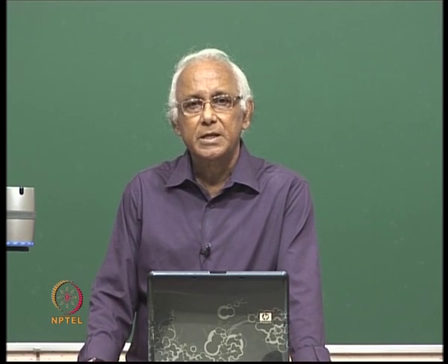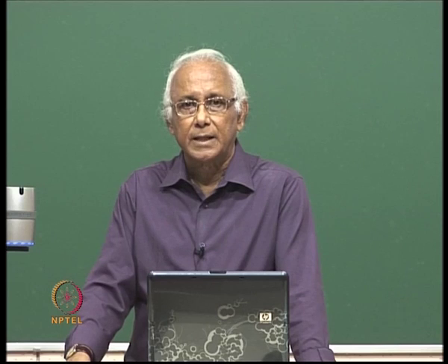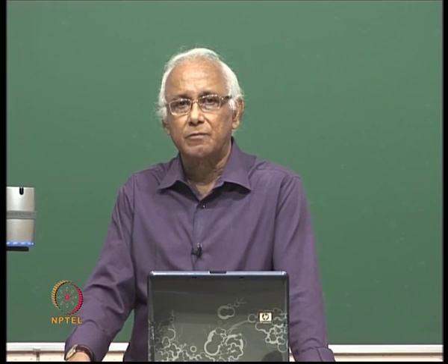Now, in a region where we have a number of ground motion records and other measured earthquake data, one can describe the seismic input as a power spectral density function, or a Fourier spectrum, or a response spectrum, or one can provide the possible peak ground acceleration and many other seismic parameters that are used as input for analyzing structures or performing any kind of seismic analysis.